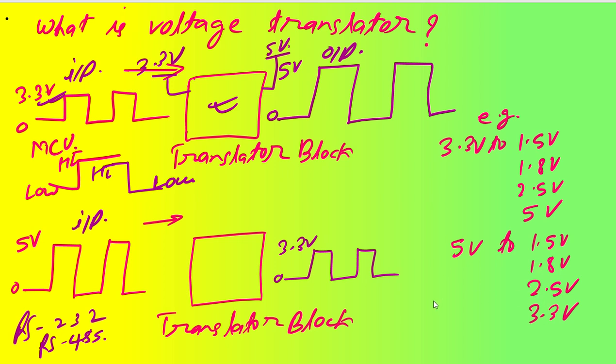This is very useful these days as a lot of miniaturization is happening, where we are shifting to lower logic levels. Earlier we were working quite frequently with 5 volt or 3.3 volt, but these days GPIOs have almost started giving a logic level of 1.8 volt or even 1.5 volt. If you talk about FPGAs, they are reaching around 1 volt very easily. So in this session, we'll try to understand these functionalities with an example from one IC, and understand the different features and circuit design considerations we should take into account.